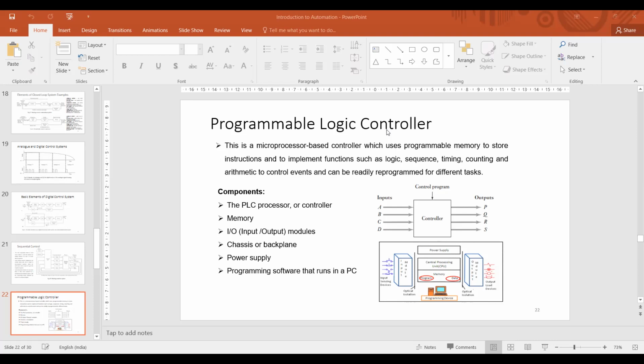If you want to do an automation where the number of systems or machines employed is limited, there you can use a PLC, because a PLC will comparatively cost less as compared to the other microcontrollers. It is very easy to understand and you can reprogram it in a very easy way. When you study ladder programming, through which we program a PLC, you will see that programming is much easier than programming a microcontroller, where you will be employing C language or related computer languages, and a software would be required for that part.